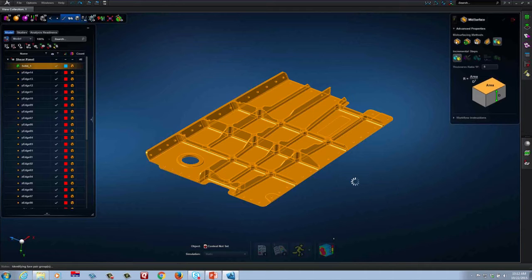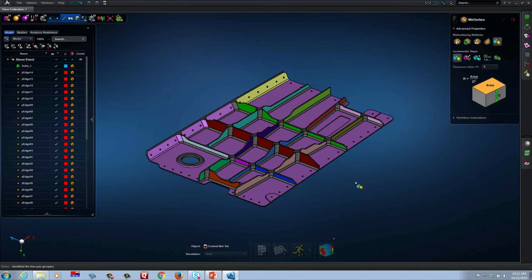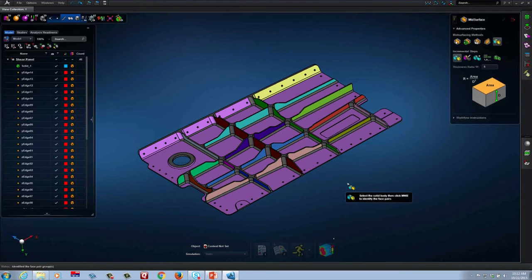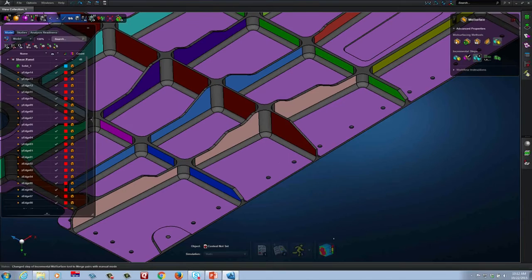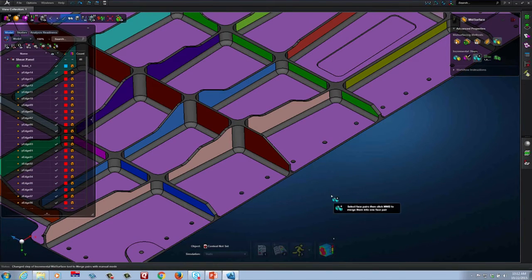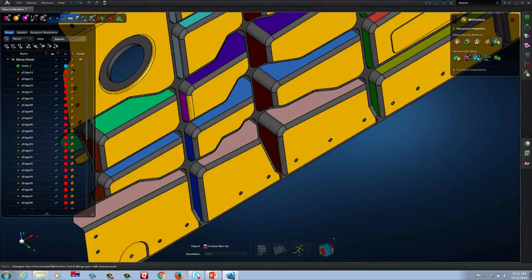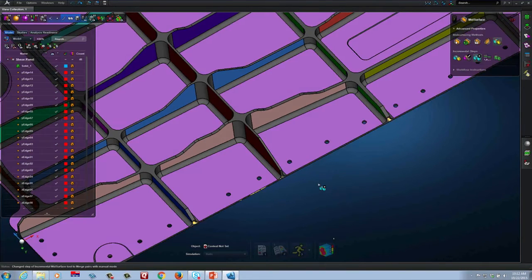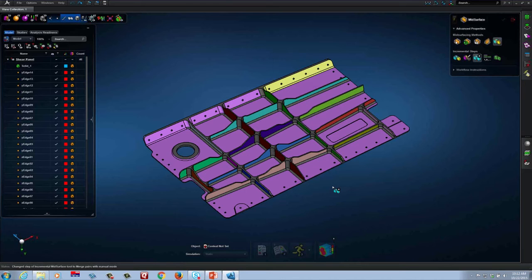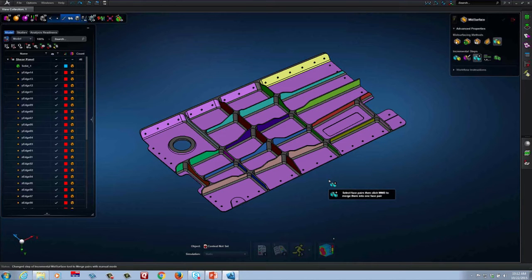The incremental mid-surface tool allows me to guide the process, okay, to introduce my engineering intent into this model. It uses the concept of a face pair. So the first step is to actually look at the solid and figure out this face opposes this face. You'll notice that I've got a lot of different colors represented here. Those represent the face pairs. And we're going to attempt to create a mid-surface between those face pairs.